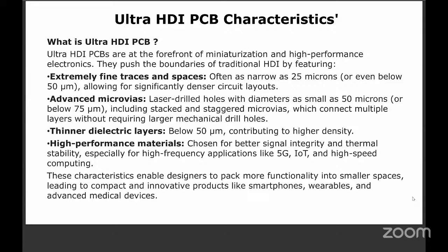And microvias less than 3 mil, 75 microns diameter. This cannot be mechanically drilled. It has to be laser ablated. And again, I want to just remind you, Rajiv, that when we say 75 microns, almost 70 microns is a 2 ounce of copper thickness, which we use in regular PCBs for power supply. So now we can imagine the size, how much it has come down to.